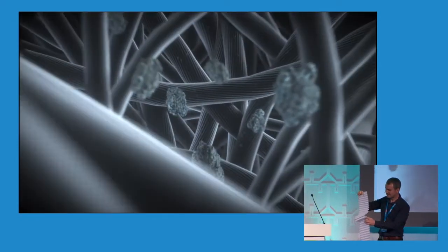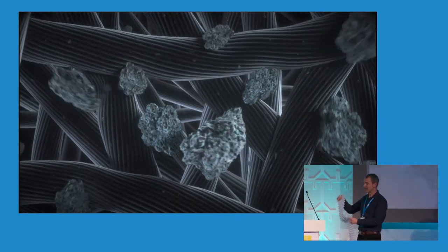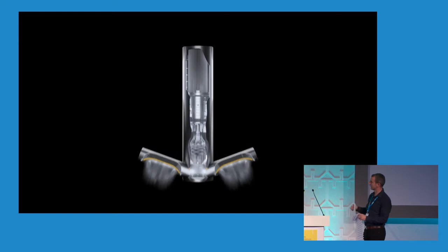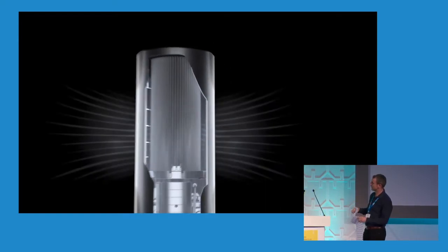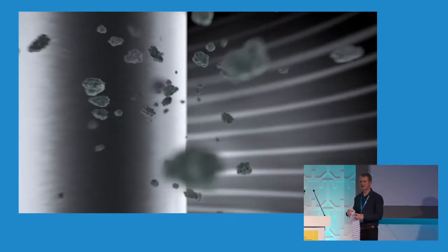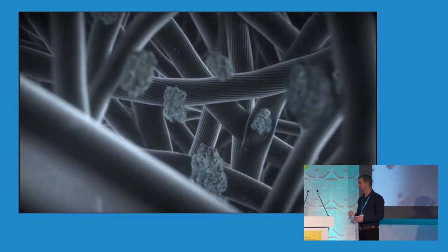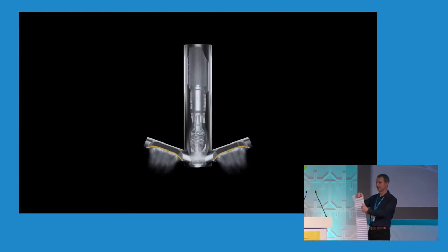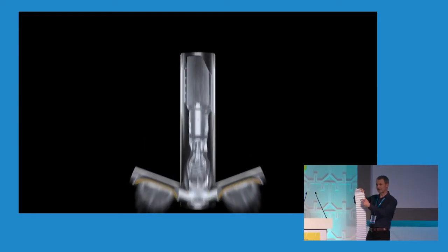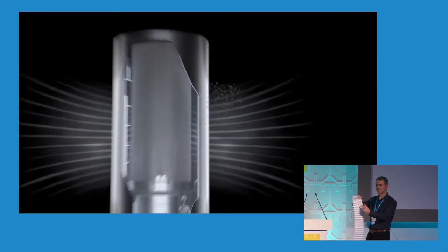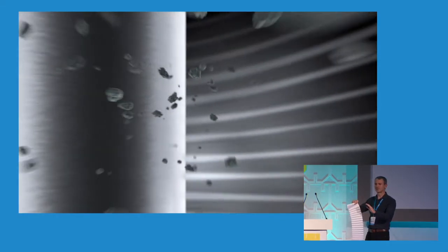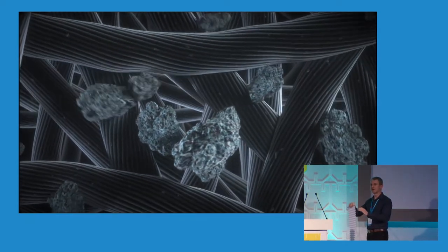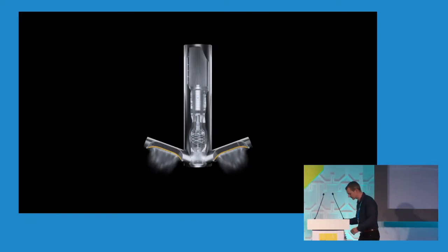What that means is that the air is flowing through that media incredibly slowly. Put it into context, the air that's exiting the blades, as shown in that image there, is coming out at around about 600 kilometers an hour, so pretty damn fast. That very same air has just gone through the filter media, and the face velocity at the filter media is about 0.3 kilometers an hour. So the difference is incredible, and that's really advantageous for us in that it really minimizes the impact of that restriction.